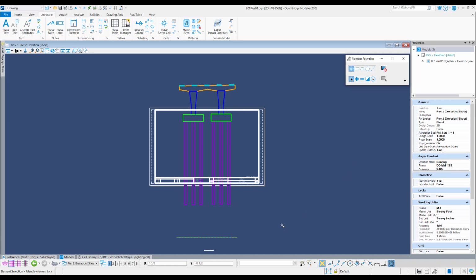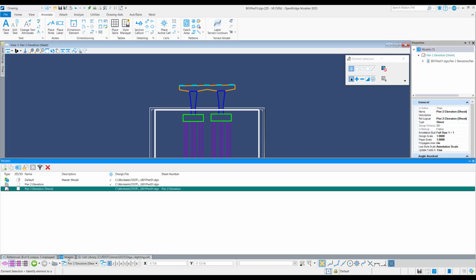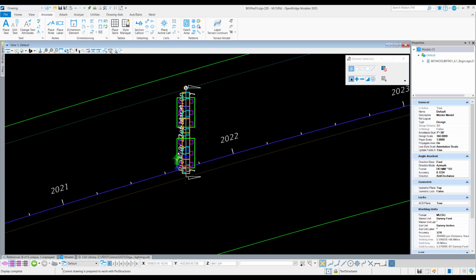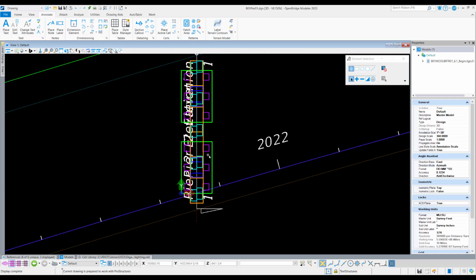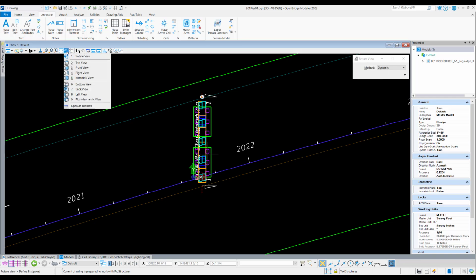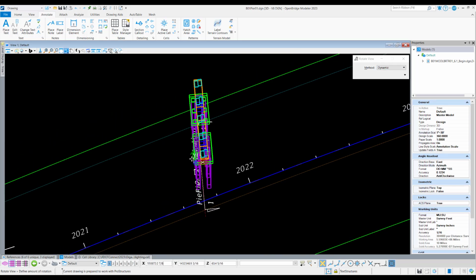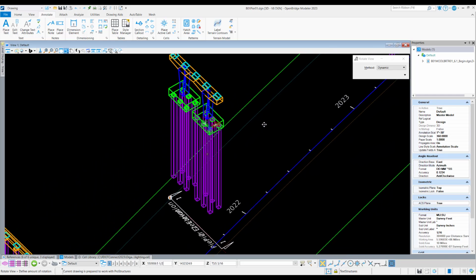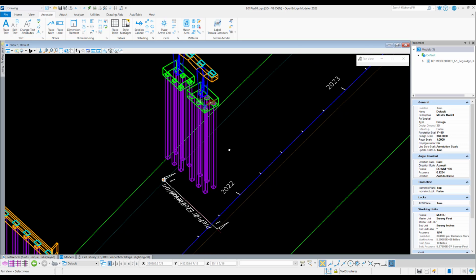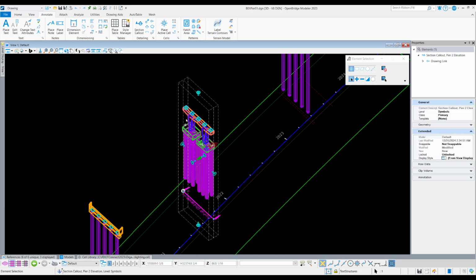So we'll go back to our default model. In our Models dialog box, we can double click Default, and then we'll rotate around so that we can see our 3D clip volume. We can go to the view rotation here, do Rotate View with the method of Dynamic, and then just rotate around. Left click and hold, rotate around. Now that we can see the section callout down here, we'll click the section callout, and you can see the 3D clip volume here.